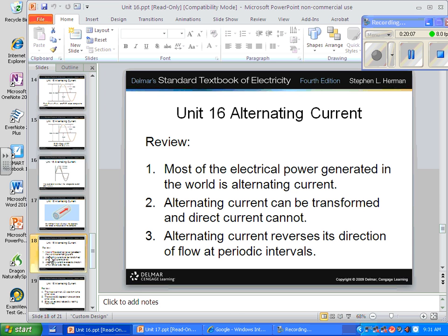Circular mill is going to be set. You can't do anything about that, right? You can, but nobody's going to pay for that. Nobody wants to pay for that. But what's the other parts of the formula? 2 or square root of 3 for 3-phase circuits, right? K, can you change the copper constant? You cannot change that. I, current.